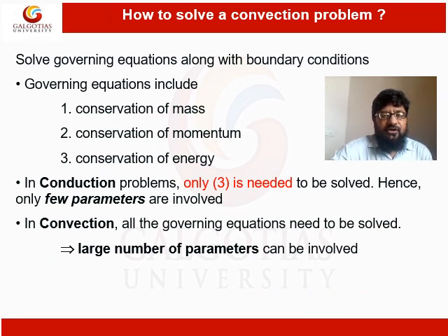So how can we solve a convection problem using the basic equations? There are three basic equations of fluid mechanics that will be used: conservation of mass, conservation of momentum, and conservation of energy. Just because in convection the movement of the fluid is necessary, we also use the conservation of mass and momentum.